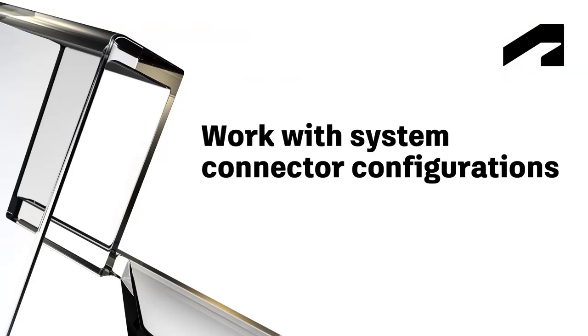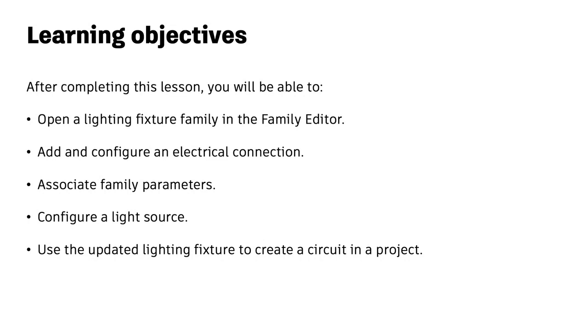In this video, you will open a lighting fixture family in the Family Editor, add and configure an electrical connection, associate family parameters, configure a light source, and use the updated lighting fixture to create a circuit in a project.